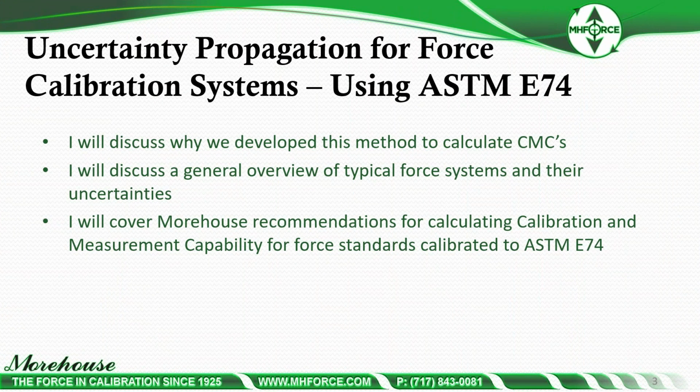So what we're going to discuss today is why we developed the method that I'm talking about to calculate CMCs. I'm going to discuss a general overview of typical force systems and their uncertainties, and I'm going to cover Morehouse recommendations for calculating calibration measurement uncertainty for force calibrations calibrated to ASTM E74.